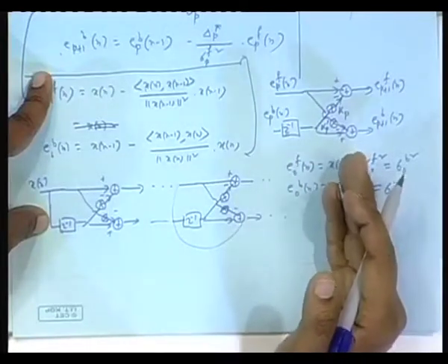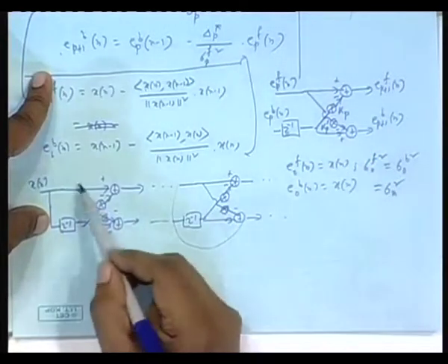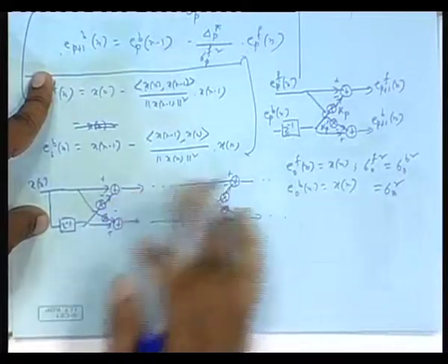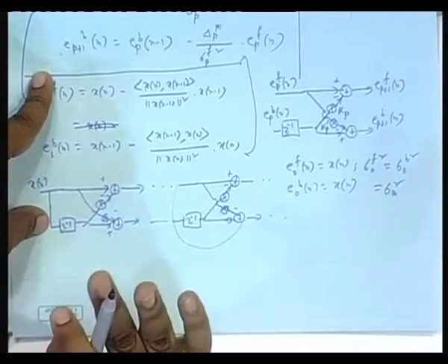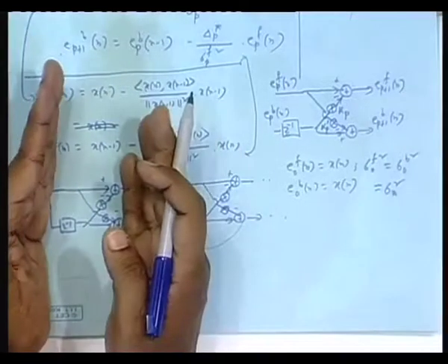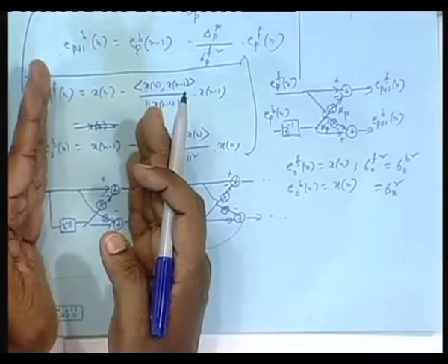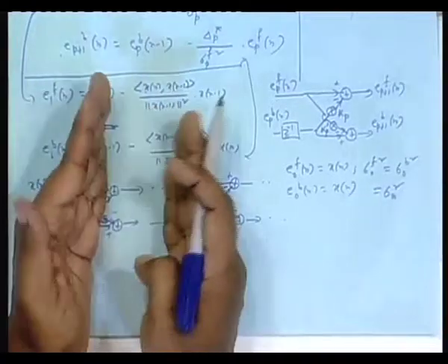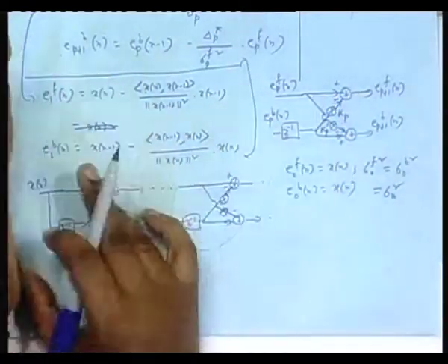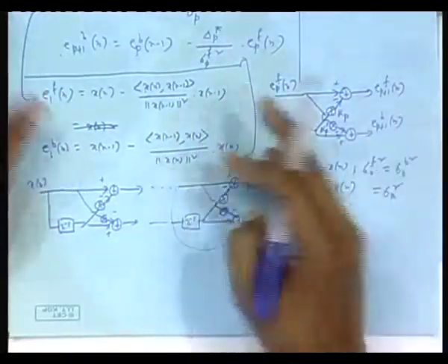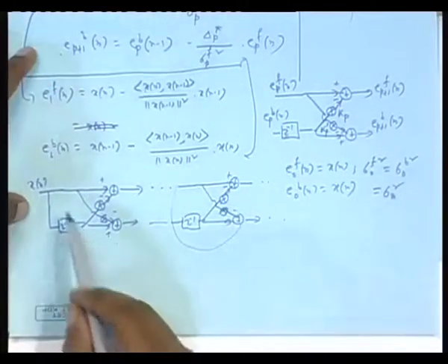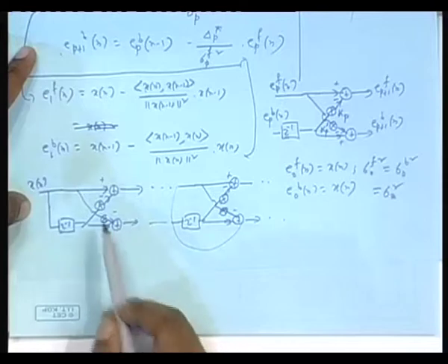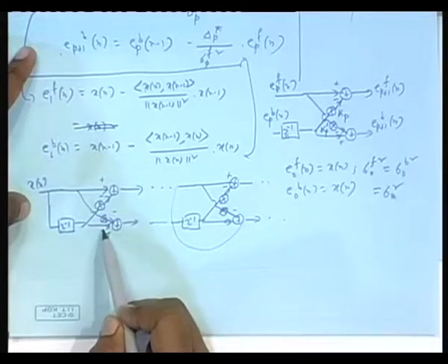So, it is very nice for VLSI. Just design the mask for this and go on repeating it. You understand? This is order recursive, very nice for VLSI. It is absolutely fantastic for VLSI realization. This one stage is to be repeated. Structurally, you are repeating the same thing. Multiplier values will be different. So, remember, you can draw this structure provided you know the coefficients, isn't it?